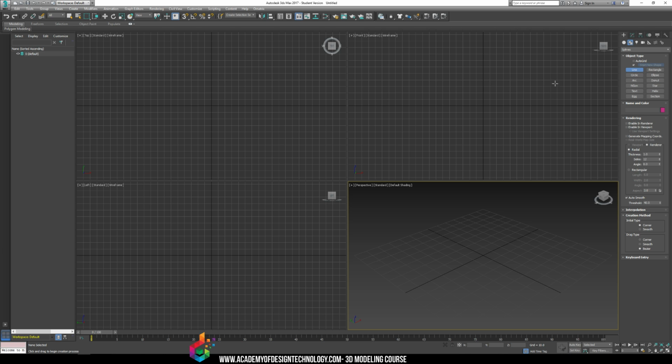Well, you can just grab the line tool, and you left click once to start the drawing. You can see it starts the drawing, and I just tap left click, and now I can move my mouse around, and you can see that I get this line that follows. Now I can left click again, and it creates the next vertex point or line segment, and then I can left click again, and I can keep going on and on like that.